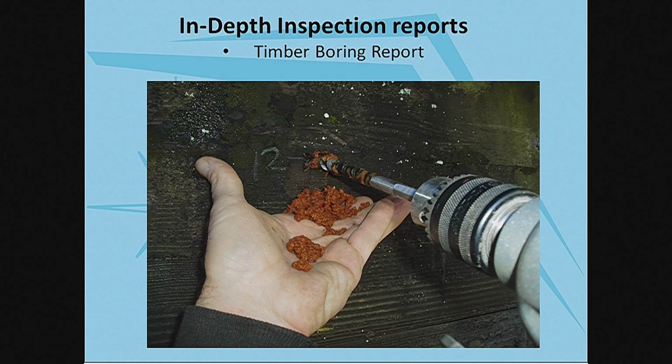The next in-depth inspection report I would like to talk about, starting with the in-depth reports that feed into the routine report, is the timber boring. Now, the timber boring report, as you might imagine, is determining the amount of decay, cracking, and checking in timber members. There are many different ways to determine that.